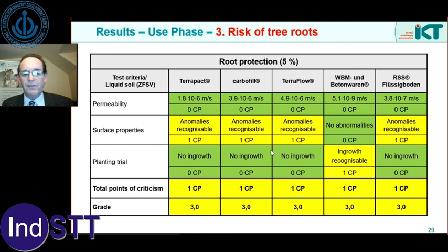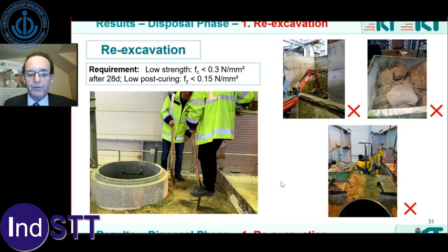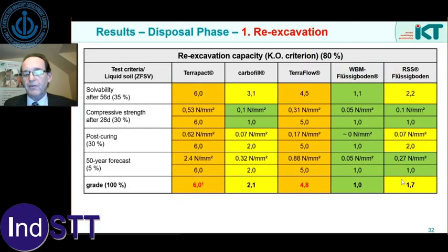When it came to disposal, we did have some issues. The steering group members went in with spades. This is them trying to dig into the surface of one of the soils, which they couldn't do. We ended up having to get the contractor in with digging gear to cut it out, and it was not successful as a consequence. So with re-excavatability, we actually had 2 products which proved very difficult to excavate, and 3, only one which was really excavatable, but the other 2 weren't too bad.